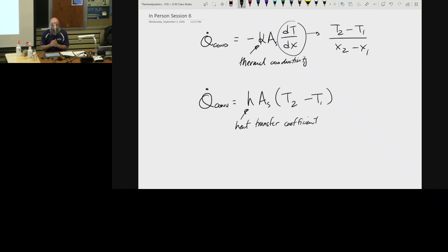So again, you need to know the surface area of a circle, of a cylinder, of a sphere. You need to know those things. They're not on your equation sheet. Please know how to do those things. In these 2 equations, the delta T, it doesn't matter if I'm dealing with Kelvin or if I'm dealing with Celsius. Those are the same step size. Doesn't matter if I'm dealing with Rankine or Fahrenheit. It doesn't matter, because the delta T is the same for both of those. All right?